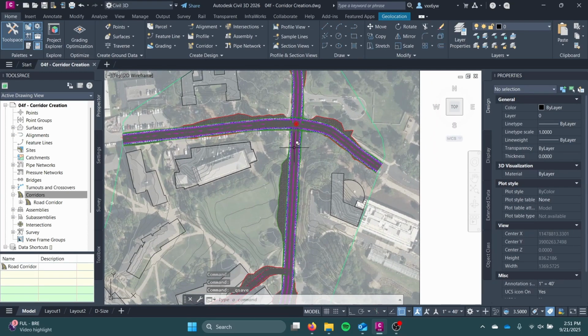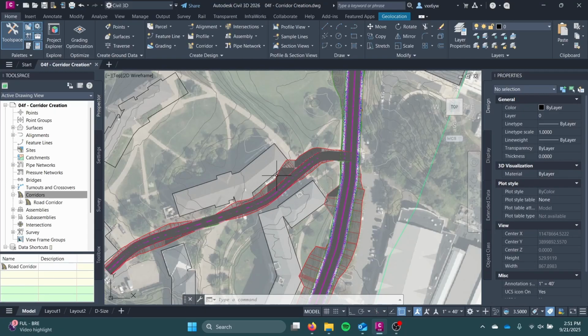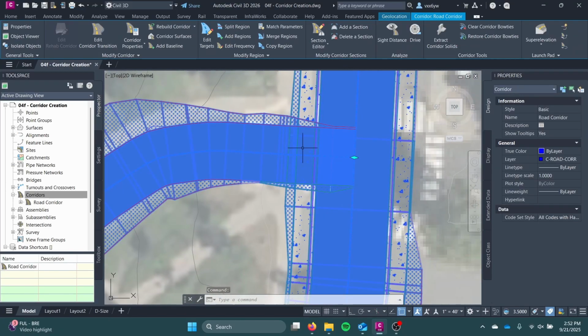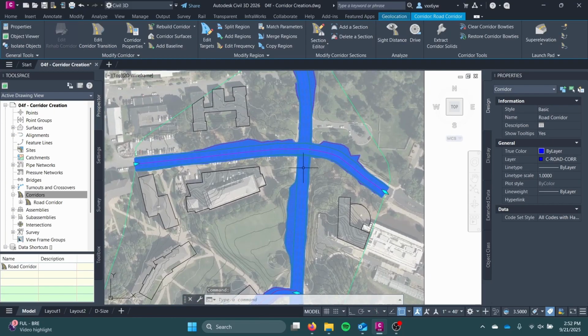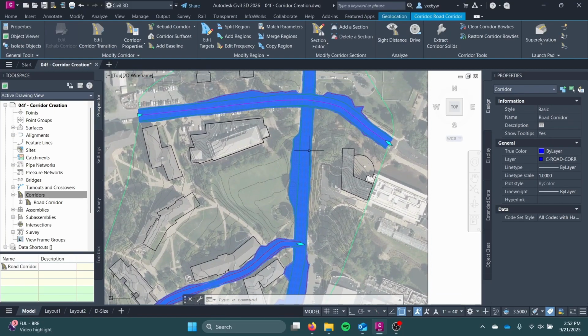So that is like part 2 of this video. Part 3 is where we will actually modify the corridors to have the right assemblies. So let's do that now. The first thing we need to do is reduce overlap here. So you can see these little diamonds that show up when you select your assemblies, and that lets you, when you select your corridor, there's a lot of different terminology here.